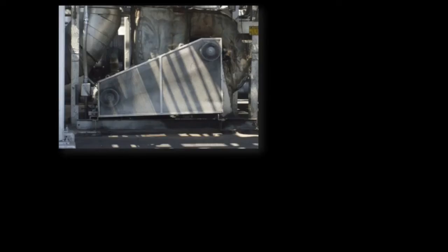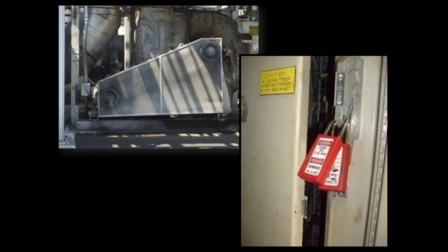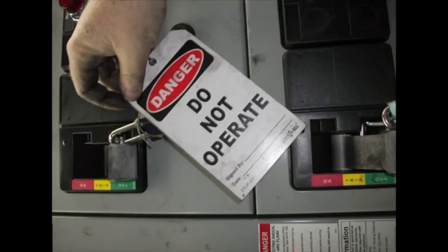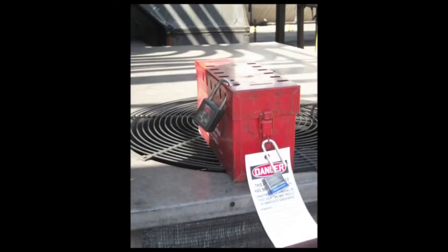Lockout-tagout is a safe work practice. Where machine guarding protects against injury from equipment that we know is in operation, lockout protects against injury from unexpected startup of equipment that we thought was turned off. At Continental Carbon, locks and tags protect individuals who are working on particular pieces of equipment. Unless you are specifically authorized, do not touch them, attempt to remove them, or attempt to operate equipment being serviced. Wait for repairs to be completed and for authorized personnel to notify you that it's safe to return to your work.